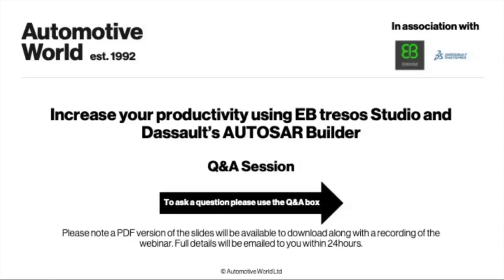Okay, thank you. There's another audience member here who'd like to know, is there workflow support for model-based development? Not sure how to answer the question because I would need some more detail. Model-based is a big topic. It can, of course, already start on the function level where you model your functions, and what's quite common here is using UML and SysML tools like Cameo or Rhapsody or Enterprise Architect. And from there, you proceed on the AUTOSAR level.